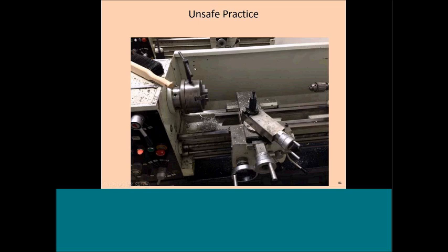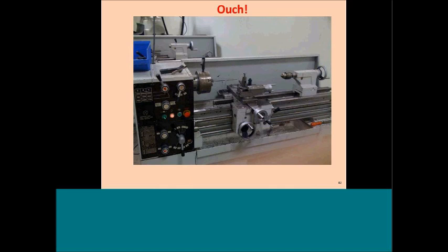Actually, what happened here is we have a capstone project, and the capstone students ran the machine that night, and they left that. I came in the next day. There's two problems I have here. Not cleaned up, and they left the chuck and the chuck key. What I've done since then, I don't know if you know they're available. Maybe you already have them, but you can actually buy chuck keys now. It's got a spring on them where you cannot leave it in the chuck. And we've got those now. So it's not going to happen. But prior to that, again, there it is again.